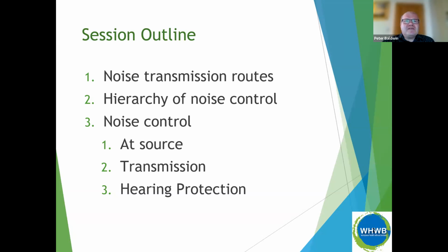And then, obviously, as in any control measure, some things are more effective than others. And so I like to talk about the hierarchy of noise control. The higher up this hierarchy you can go, the more effective the control will be. And also, it's an easier way to control it, say, at source compared to control at the individual level.